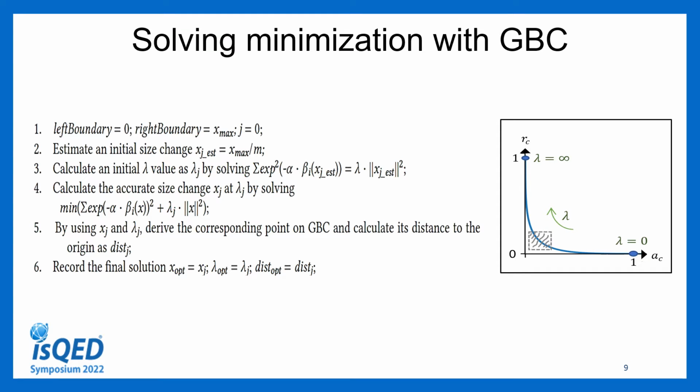A major difficulty that designers face is to develop systems or models that perform reliably in the event of process variation. Design centering addresses this issue by finding a design that meets specified requirements with high chance of doing so even if the parameters change randomly. Design optimization tries to identify the design that best satisfies the specification. However, design centering seeks to find the design that robustly meets the specification. So we use design centering to achieve a robust circuit design and the best yield functionality while having a safety margin in our parameter distribution.